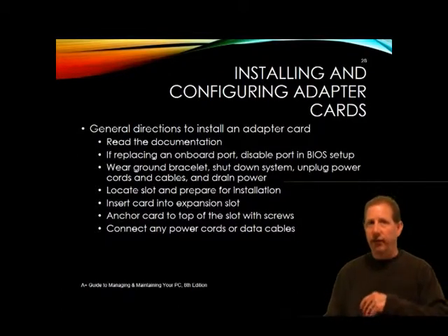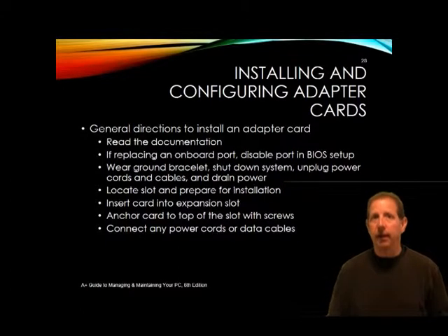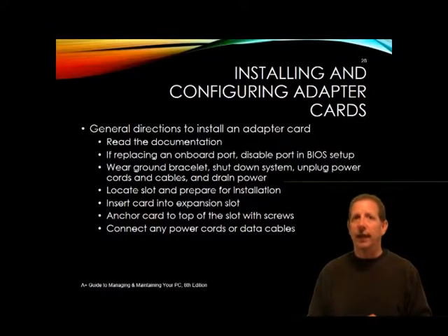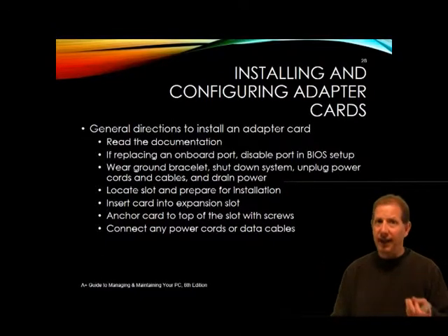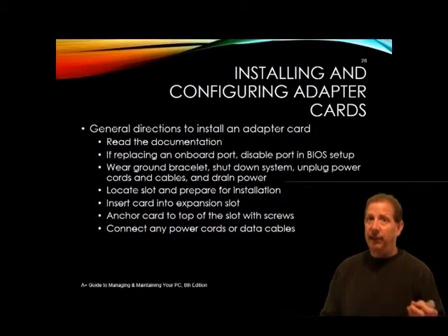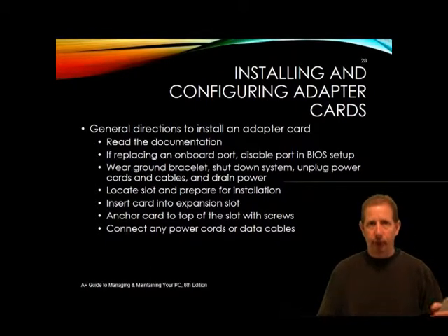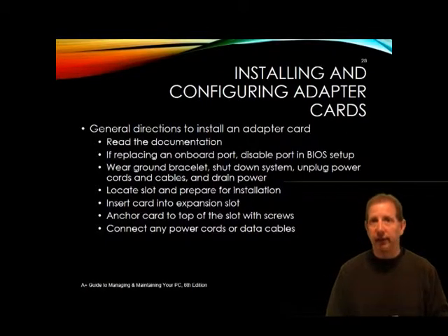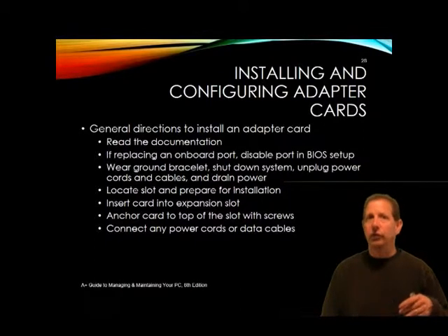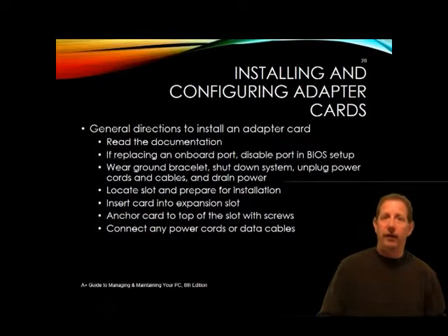So for example, if you're putting in a video card, you might have a 6 or an 8 pin PCI Express power connector off the power supply that would need to be plugged into that card. If the power supply doesn't have the right connector, perhaps you can buy an inexpensive adapter to convert the 4-pin Molex connector to the PCI Express connector if need be. Okay. Make a quick check of all the connections and the cables and then replace the case cover. If you want, and if your system will allow you to, you can leave the case cover off in the event that you need to reinstall the card if it doesn't fire up the way you want it to.